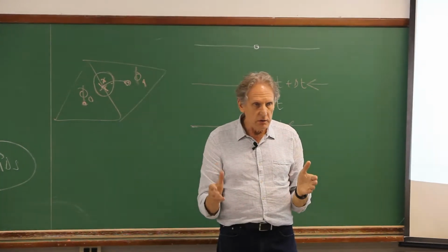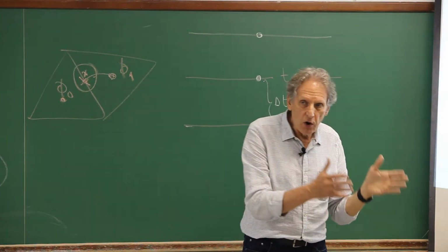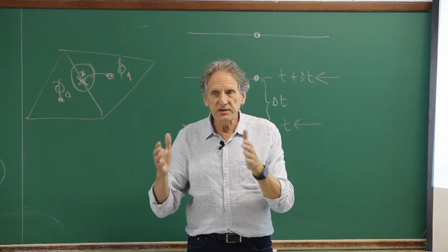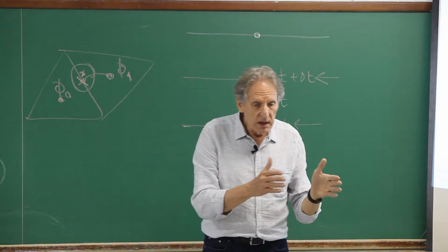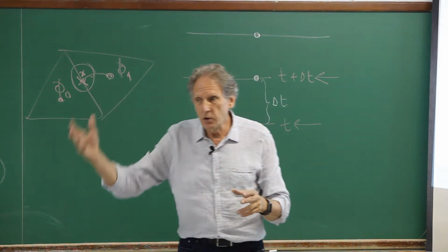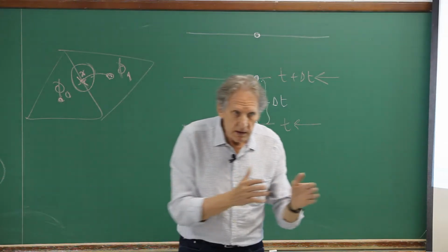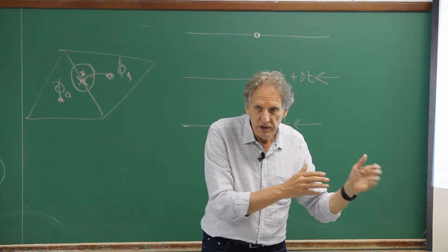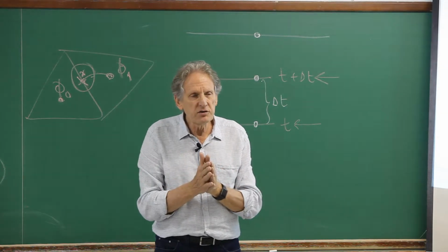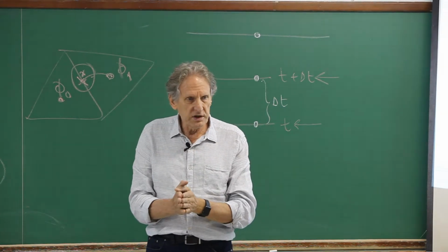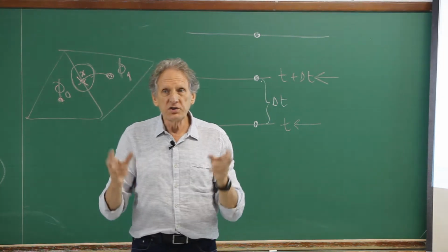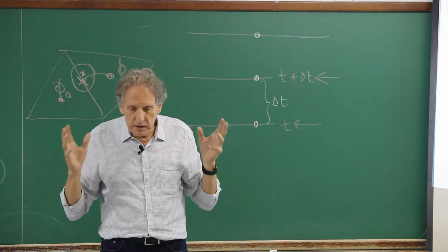why are you solving your equations? What is your problem? What is your engineering problem? Does it accept some smearing of the gradients, but you are interested in the overall solution that can help you solve your engineering problem? Then use upwind. So there's no strict rule that I always have to get a solution with second order or more.